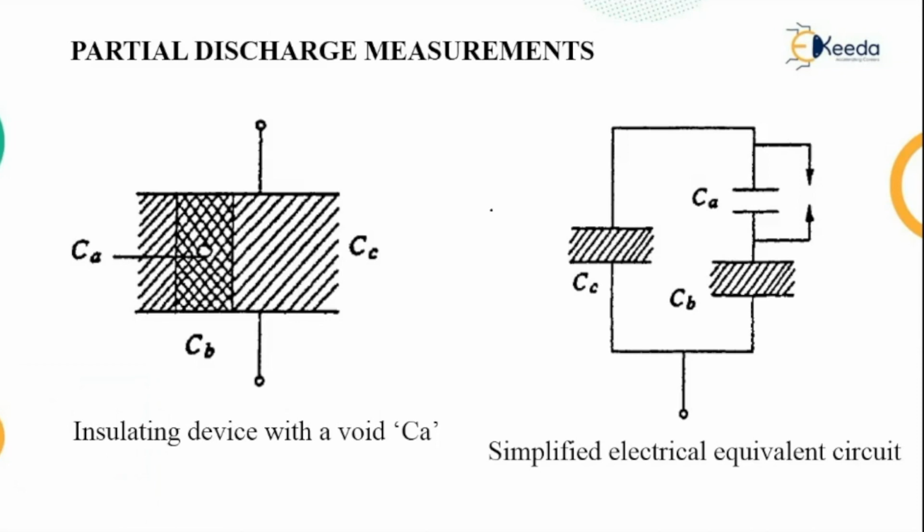In further investigations, it was found that weak points in an insulation like voids, cracks, and other imperfections lead to internal discharge in the insulation. These imperfections, being small, were not revealed in capacitance measurement, but were revealed as power loss components contributing to an increase in dissipation factor.